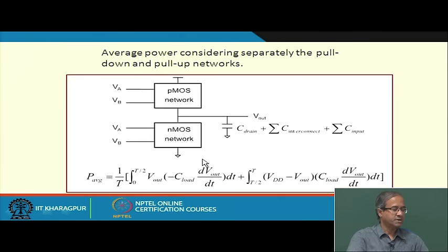Yes. So, just recalling the power consumption in a CMOS network. I have this PMOS, NMOS, this is ground, this is VDD. Earlier I had shown only the load capacitance, but in practice this capacitance will be the sum of several things.